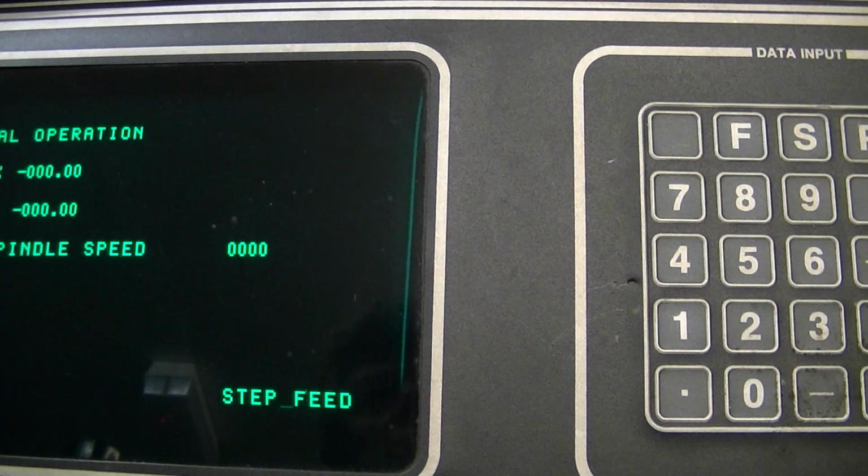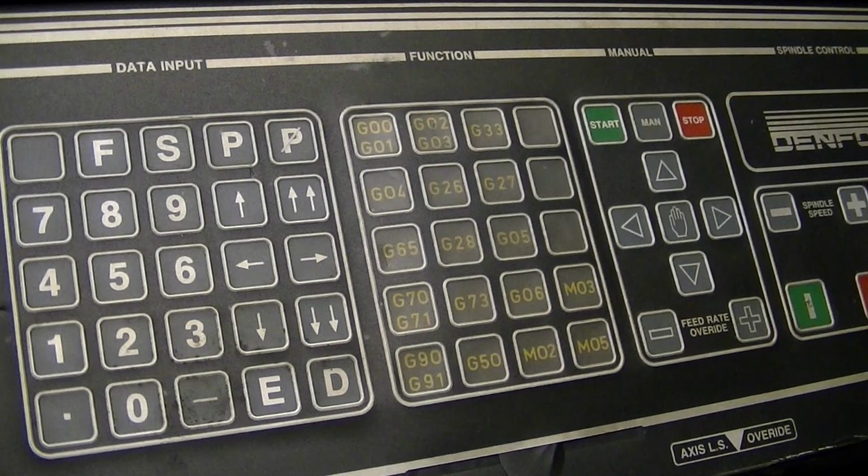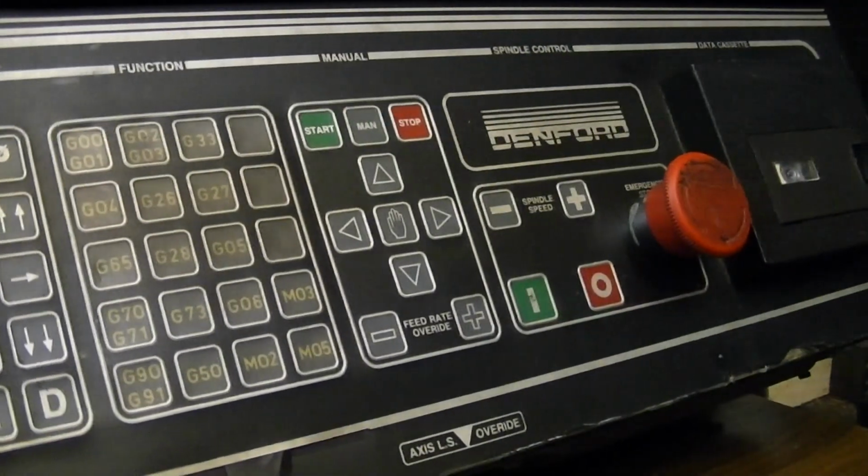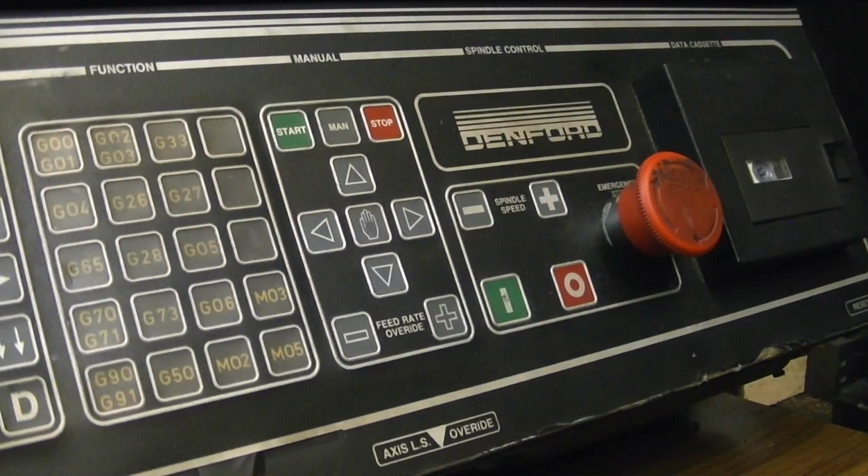Now, because I've already set the tool cutting point up to be in line with the end of the face bar and at the set diameter, we don't need to do any of the manual cutting. So we need to get into the CNC programming mode. To do that, we move over. There are two ways that you can do it.